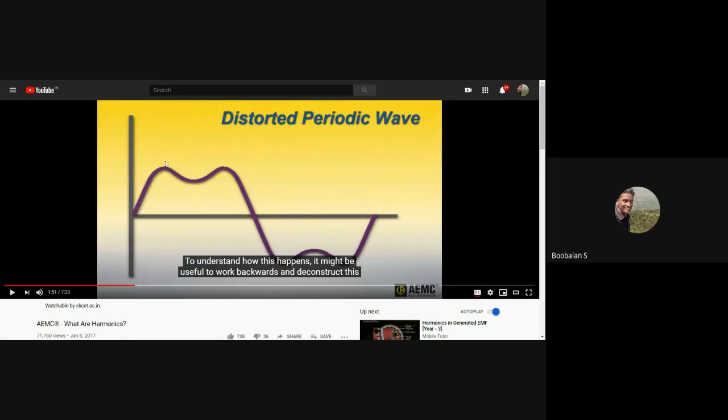So due to my switching devices, right, my voltage is now getting disturbed. It's not a pure sinusoidal. We have seen pure sinusoidal waveforms in textbooks and online resources, right? But by seeing the original waveform on a power quality analyzer or power analyzer, with the help of some instrument, you couldn't have that exact AC sine waveform. We have also seen it on the CRO in our colleges. It's not a pure sine waveform; somewhat it's going to be distorted, right?